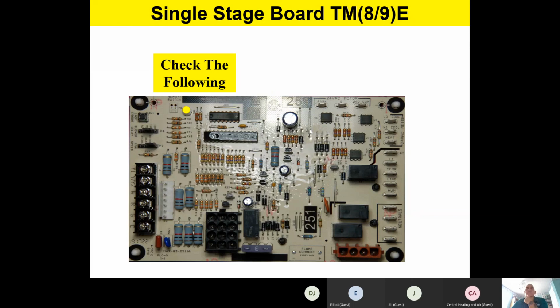Page number 21. All right, team. Well, a continuous amber flash is low flame current. So if you have low flame current, it'll give you a fast, continuous amber flash. The most important thing about low flame current, the very number one cause for low flame current, is poor grounding. So make sure that your ground is very, very good on the furnace.